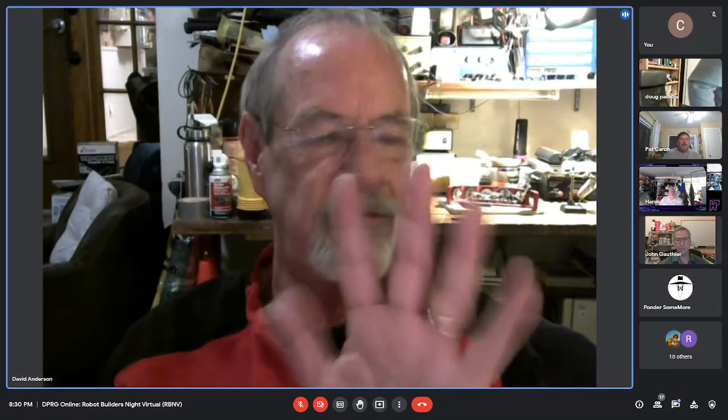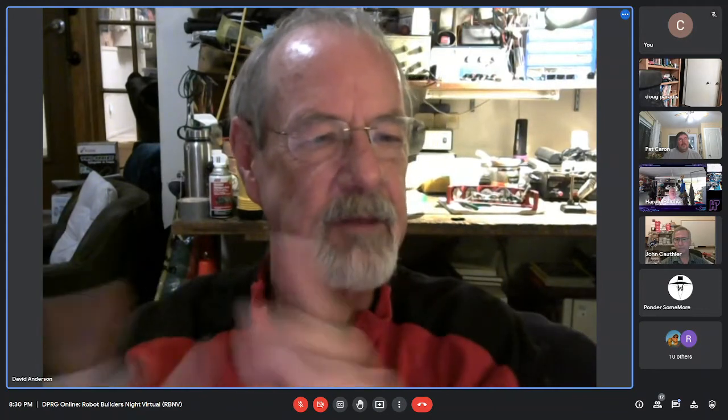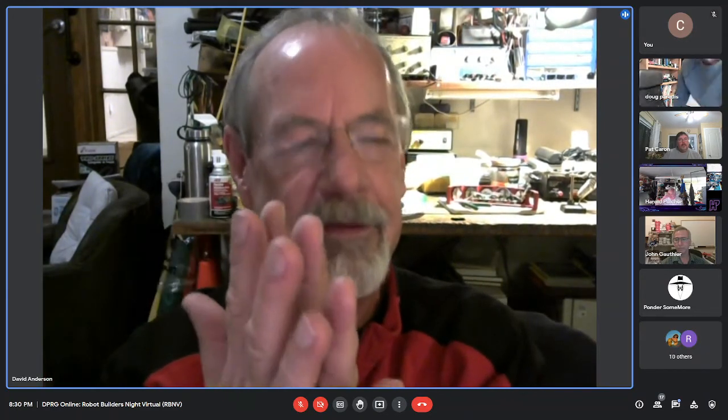When I was saying that it was useful to have the wheel odometry also, I think I talked before about how you're only using the distance, not the angle calculated from the wheels. You're getting the angle from the IMU or the gyroscope. Even so, you can compare the two of them, and they should most of the time be pretty close to the same. That is, what the wheels are saying and what the gyro is saying will not be exactly the same, and if you integrate them, they'll drift apart. But they should instantaneously be about the same most of the time.